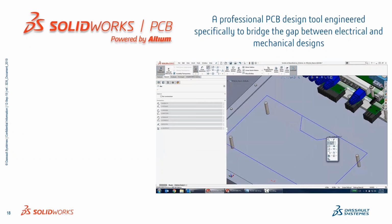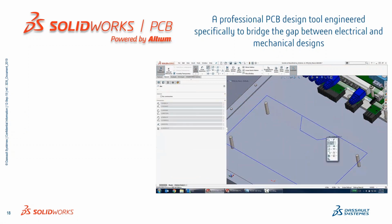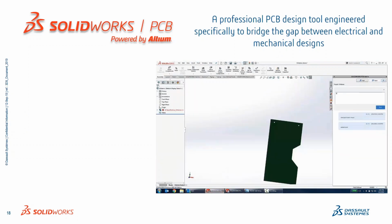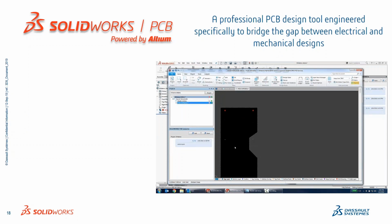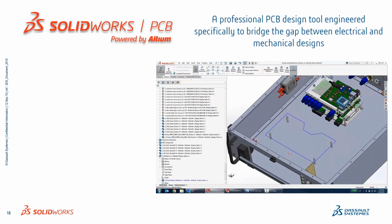The other tool that I work with is called SOLIDWORKS PCB, and that's this tool right here where I can take a circuit board and actually design the shape of the board in SOLIDWORKS, because a lot of times that's where my constraints come from, and that's where my keepouts come from, and that's where certain information about my design comes into play. And I can push that information over into SOLIDWORKS PCB, which is a separate tool. And we can see here that that board shape is now available for the PCB designer to work with. So now there's less iterations going back and forth between those two sides.